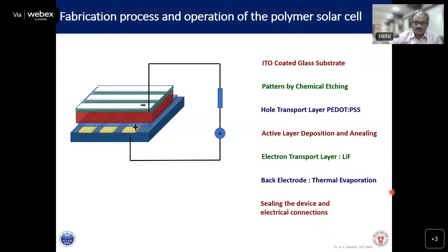Now you put contact wires here, because this is aluminum, you can have a direct contact here. Similarly, for ITO you can make contact with gold deposition and a gold wire. Then the exciton is first created, and suppose this exciton is dissociated. In that case, the electron hole pair is separated, and this moves through an external circuit to give a current.